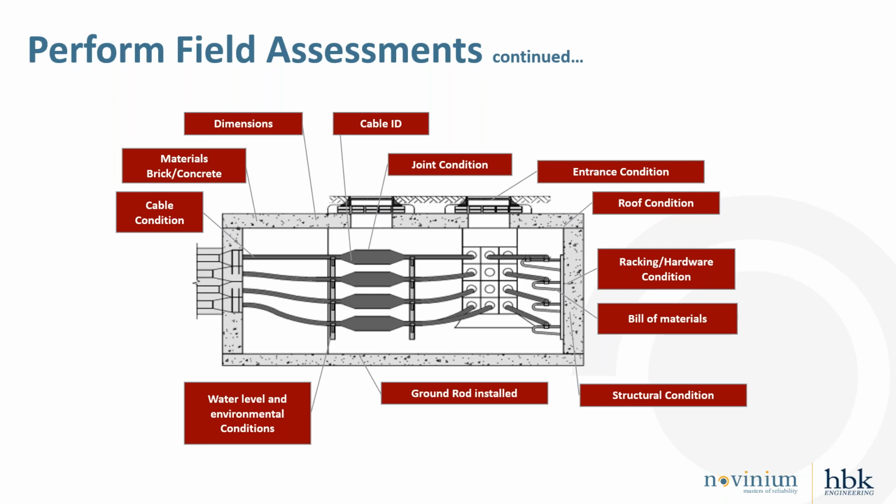The hardware in the manhole is also inspected, and in this case, we treat it as a bill of material, listing the quantities of deficient materials for replacement. The assessments identified things such as deficient channels, brackets, missing saddles for cables or joints, missing sump covers, and pulling eyes.